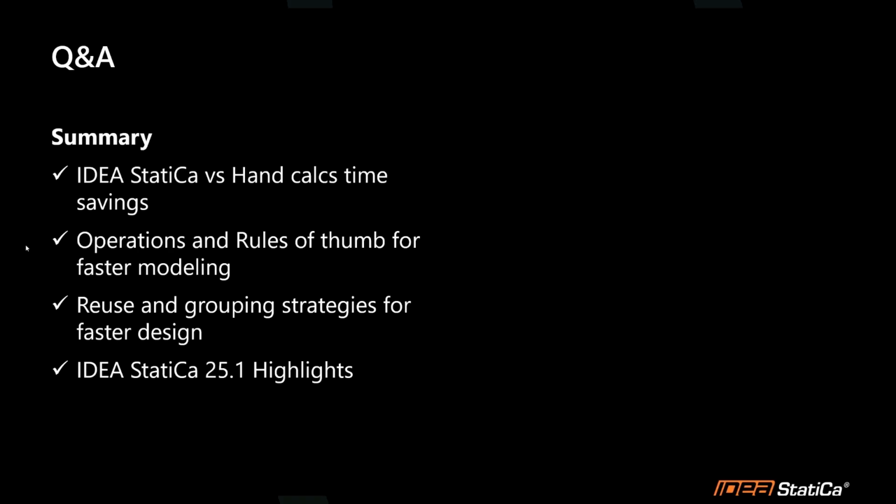We also had a question whether we can import custom shape cross sections for things such as historic retrofitting, things like that. And the answer is yes. We are able to import custom shapes not only for the cross sections. If you have, again, any custom geometry on your plates or things like that, you can always import those. But again, we also offer the options where you can customize and edit your common rectangular plates.